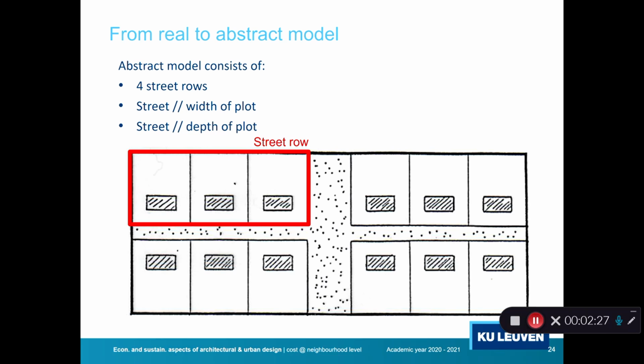What you will do then is you will make an assumption and position this building in a repetitive neighborhood as is shown here. So you assume a number of buildings in a street, and the plot size should be more or less identical to your real plot size. You will assume the streets surrounding this building and translate them to rectangular streets. So the length of the street and the area of the real streets will be important to translate it in a correct way.